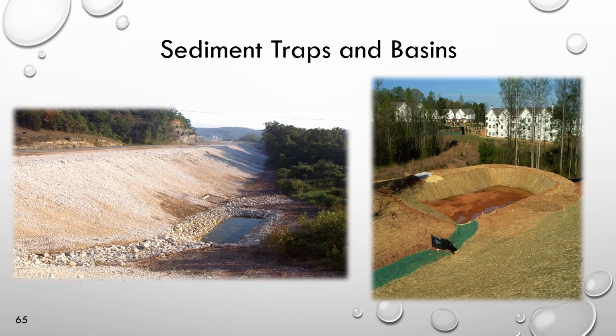Another example, again, sediment traps and basins. This is kind of bread and butter for flock logs. Most of these have a channelized area that's going to direct the water into these basins. Again, if we have small clays, they're just going to sit there and we might not get to a low enough turbidity or TSS to where we can discharge the water. So adding flock logs or granular into those conveyances that lead to the basin, we're treating the water, forming really large particles that can then settle once the water enters the basin.